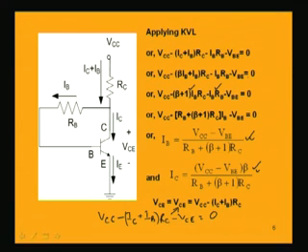So, let us find out how the change of beta is going to affect the collector current. In this expression, it is very clear that beta is there in both the numerator and denominator for this expression for IC. So, definitely it is very sensitive to beta variation. Now, if we can design the biasing scheme in such a way that we can have the expression for IC getting rid of the term beta in the limiting condition of some design specification being met, then we can achieve that.